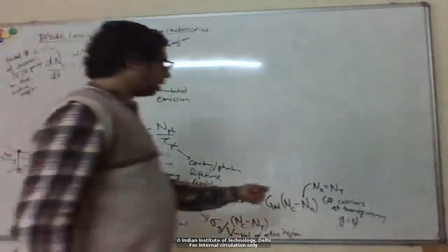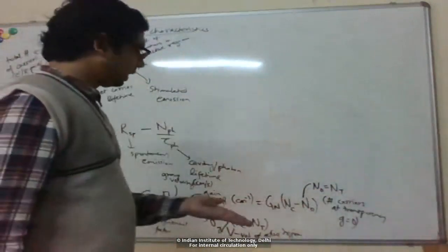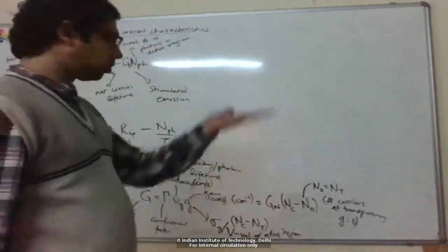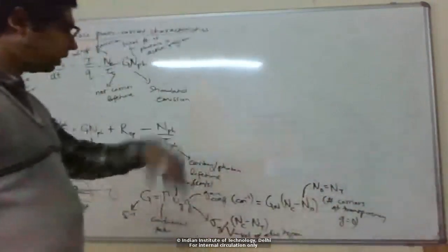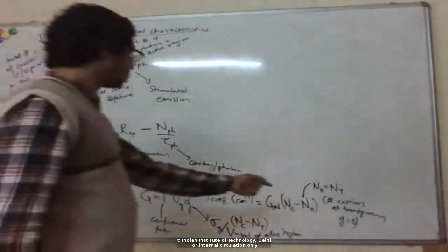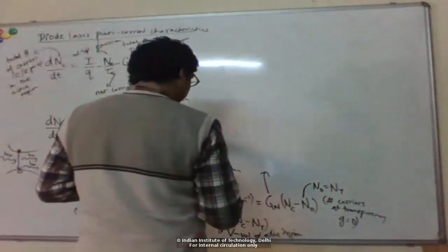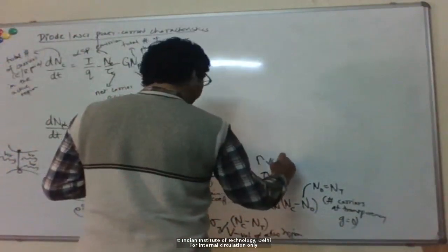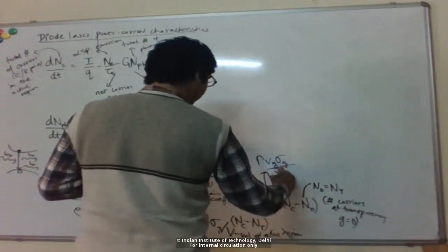So this is the number of carriers in the active region that you need to just be at the threshold of population inversion. Now you have an equal number of carriers in the excited state and ground state, so that absorption is equal to emission and gain is 0. Beyond that, you start getting gain. And this Gn is a constant which depends on, you can see, confinement factor, group velocity, this cross section divided by active region volume.